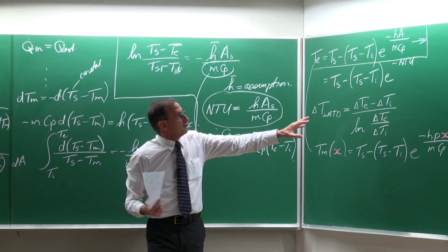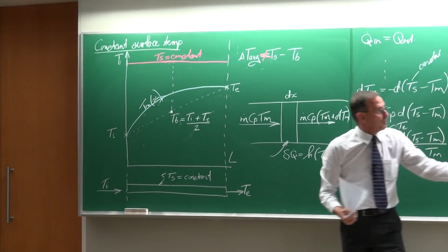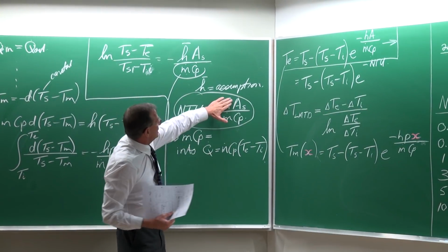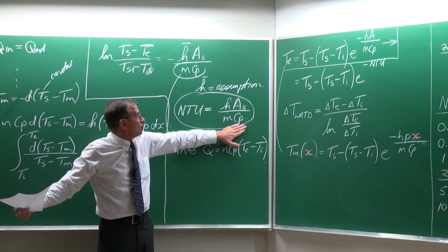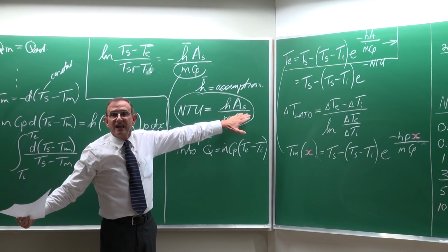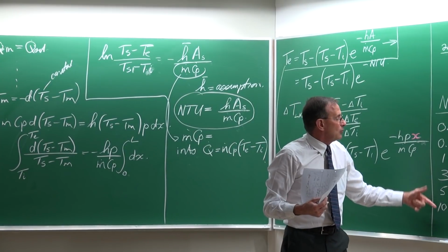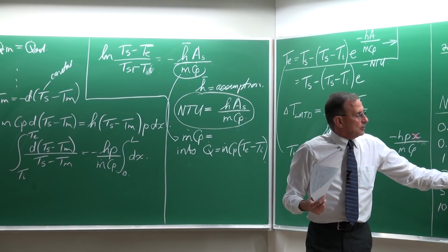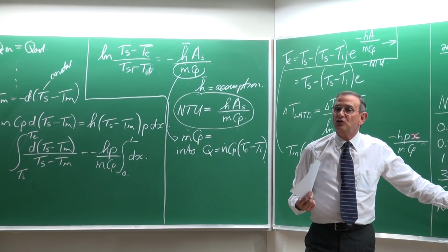Now let's suppose you had a tube with a constant diameter and the flow was fully developed, then you would know what the heat transfer coefficient is, and the mass flow rate would be constant, the Cp would be constant, so it is actually the area. You need to increase the area by 3 times to increase the outlet temperature from 99.2 to 100.